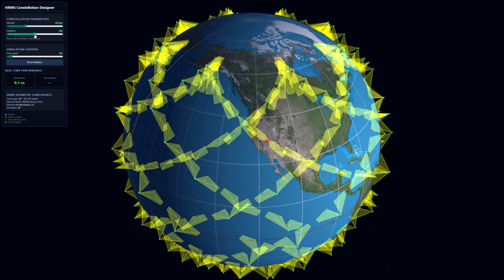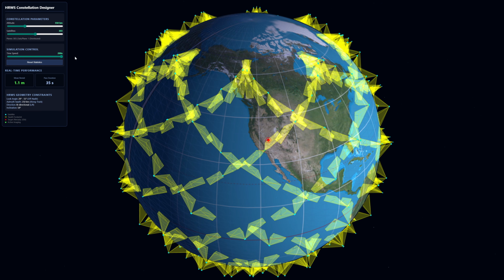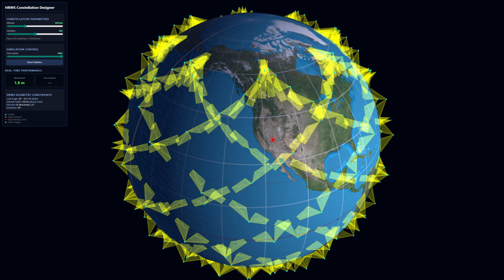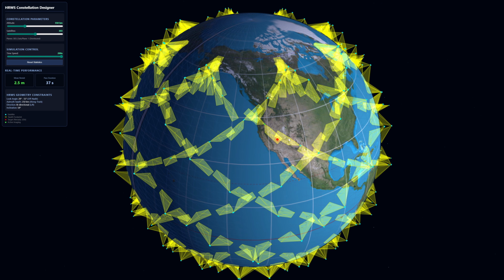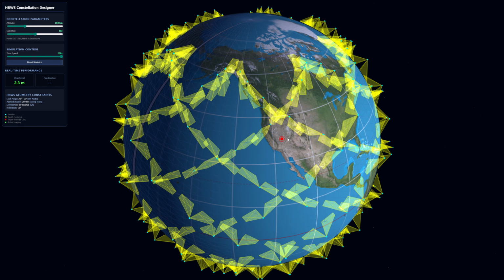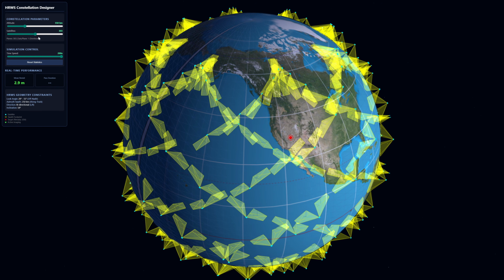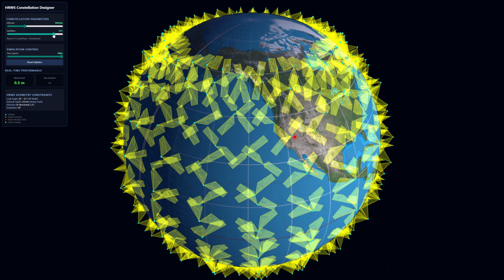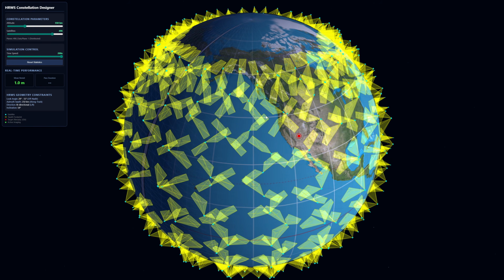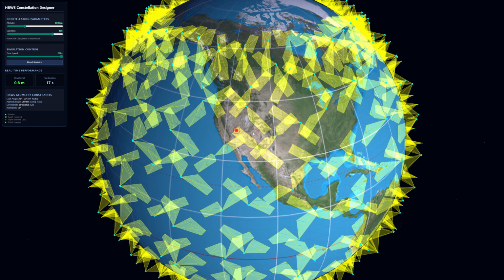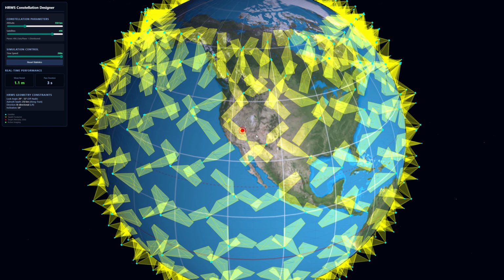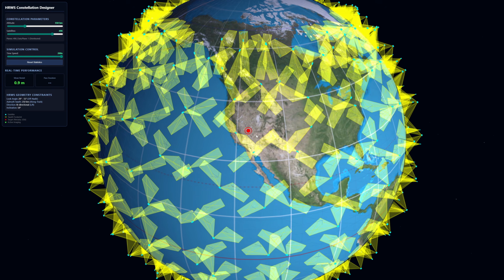On the screen now is a simulated view of a constellation of these satellites, and similar to my spotlight demo, we will need around 500 satellites to produce ideal revisit times of a few minutes, which would be the near persistent detection required to tip off the VideoSAR mode satellites of high priority targets. I assume that this mode will not use any squinted geometries and that the azimuth swath will be 250 kilometers across, which is the azimuth swath of NISAR.